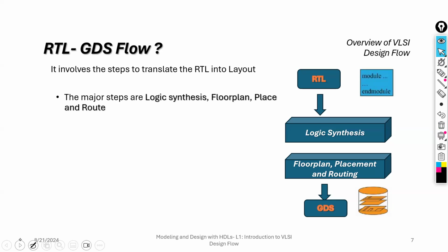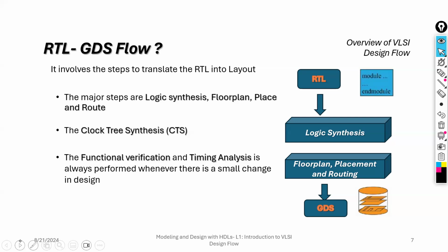In addition to these steps, another important step is clock tree synthesis. Of course, it's a very, very essential step for any IC design. And we always do this kind of step that is called functional verification and timing analysis. Whenever you make some kind of change in the RTL code, whenever some kind of modification in the placement, floor planning and routing, definitely we have to perform functional verification and timing analysis.